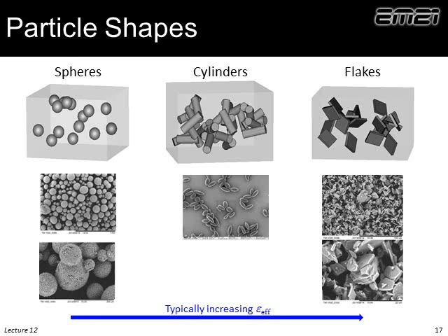Particle shapes. In terms of ease for manufacturing, making materials that are robust and just work well mechanically, we like spheres. Electromagnetically, spheres don't work so well. We get a very weak response from the spheres. And it turns out we want a very irregularly shaped particle. And in fact, flakes is one of the best particle shapes we can get electromagnetically. That perturbs the field more in the vicinity of the particle, and we get a stronger response.